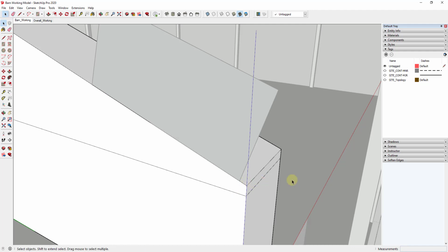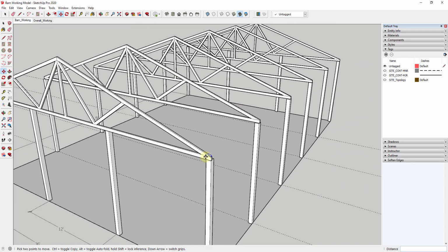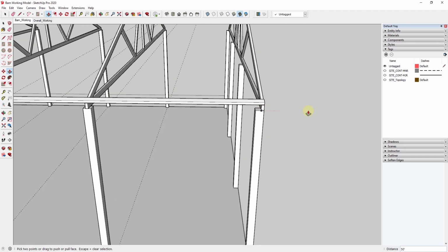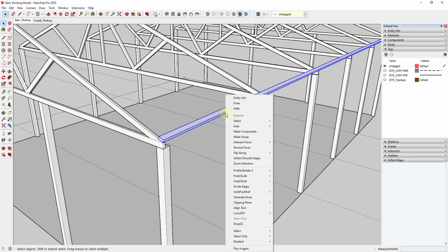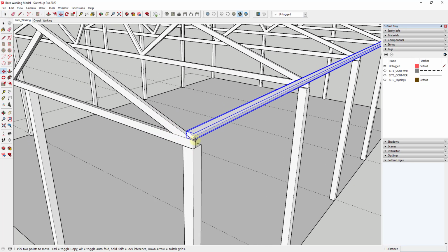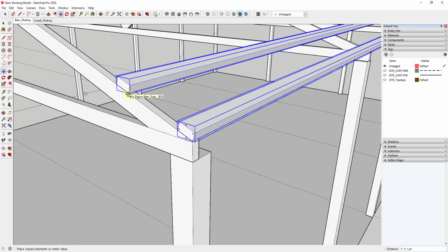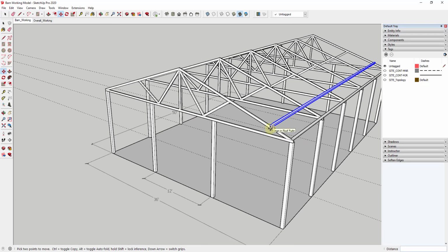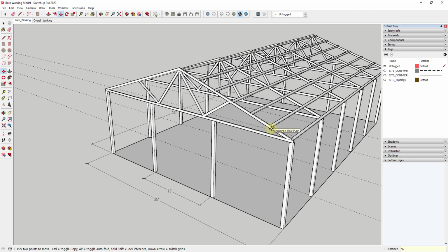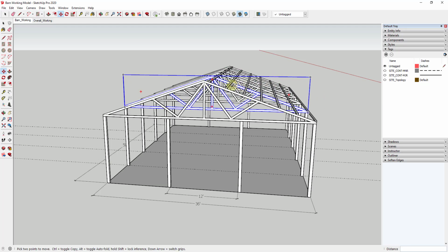And I'm going to go in here and clean this up just a bit. We'll take this and move it down so it's actually aligned at the corner, and then I'm just going to extrude this across using the push pull tool, like this. And then we're going to triple click on it and make it a component, and we'll just call it roof purlin. Then we just want to use the move tool in copy mode to create a copy of this 36 inches from your base point. So you'll just activate copy mode, move your mouse here, and type in 36 inches, and then type in something like times 10. And notice that this kind of moves around, so you can do a times 5, times 6. So as long as you don't click anywhere else, you can take that whole thing, or you can adjust it by typing in a different value and the enter key.